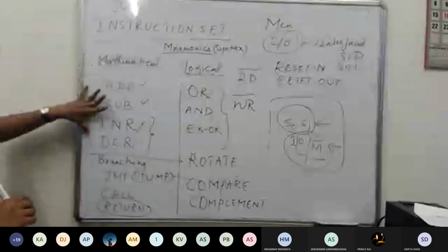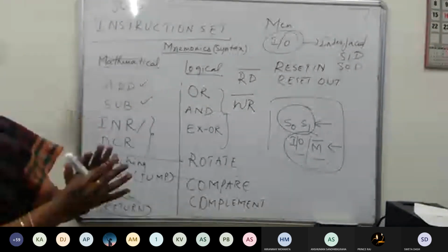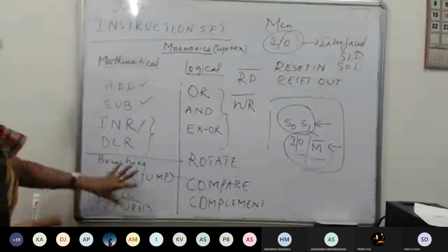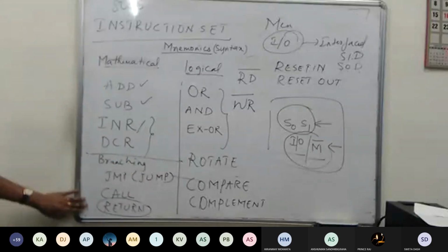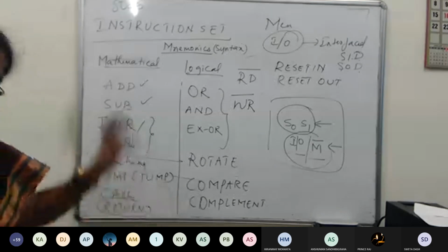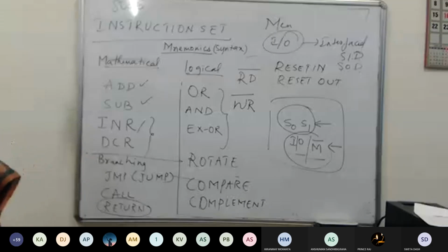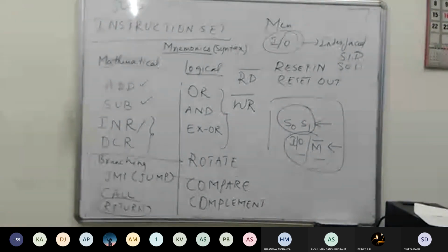This is how we have to enter into the 8085. These are our methods. The mathematical operations, this much I can do. The logical operations, this much I can do, and that too only on bits. And then this many jumpings, the branching operations, I can do. With this only the code has to be written. And by the way, the memory size is only 64K. The instructions have to be in that, the execution also has to be done, and the results also have to be allocated in that 64K, not more than that. Correct? Yes or no?